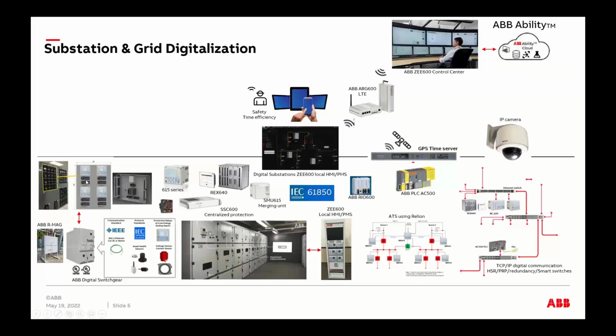At the same time, you're thinking about other stuff, meaning protection and communication. You're thinking about fiber laid down in the substation. That's a given. Within the substation, typically that's the best solution you will have. Maybe you're also thinking about upgrading your PLCs. Existing PLCs on brownfield substations you will see as analog, and now we're talking about digital PLCs. Maybe you're also thinking about doing a soft communication PLC.